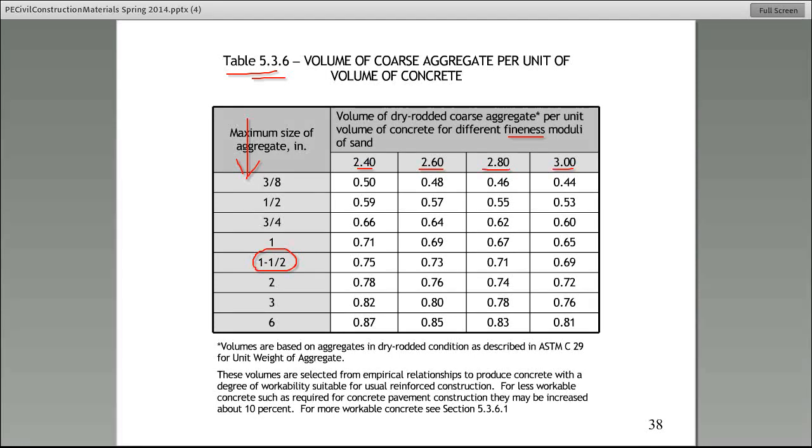So in this case, help me out. What is the fineness modulus for the sand that we are using? Mary, maybe you can look it up, or Helen, or Joe in El Paso. By the way, El Paso is one of my favorite cities. So here, 2.8. Yeah, okay, thank you. Many of you are telling me Matt said 2.8. So in this particular case, it's specified that the fineness modulus of the aggregate is 2.8.